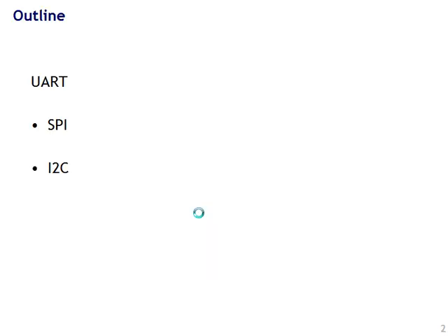So a couple or three common serial communication interfaces that you have to care about when you're going to be a designer of computers. One, the UART, that's the serial port, your COM port, or your RS-232 interface, or your RS-422 interface, all through the UART. The other, SPI, that's a serial peripheral interface, and that usually comprises a master and a slave.